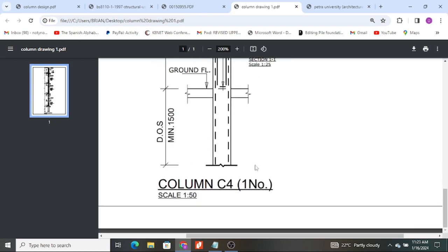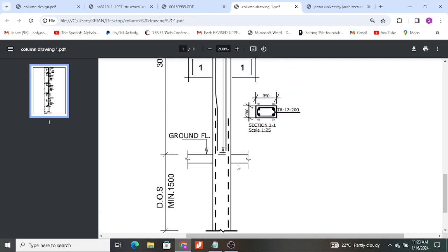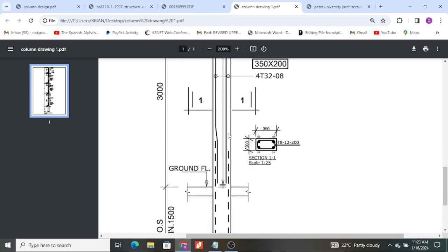That is the way we do it, but sometimes you can draw it and attach the footing to it at the same time. Also, you need to show the cross sections at every column, but I wanted to show you this so that I can show you there is something missing. This is a bar from the substructure. You also need to dimension the overlap length. The overlap length is very important. You need to dimension it so that it's clear to the fundis, those who are fixing reinforcement on site, how to do it.